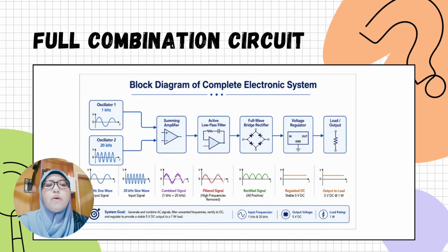Since the output of the rectifier still has ripple, a capacitor is used to reduce the ripple voltage to get a smooth and more stable waveform. After that, the DC signal is passed through the voltage regulator. Its function is to maintain a constant output voltage, and the design's regulated output is 5 volts.